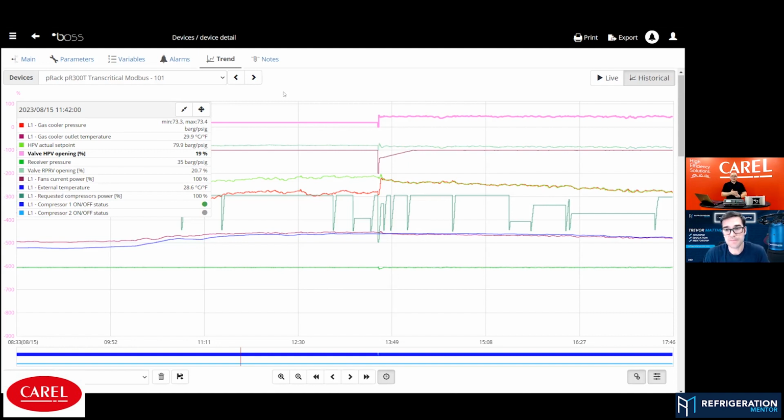Not really, not really. The problem was our friend in the service was a bit stressed and nervous. Yeah, and fair. He put up the motor of the valve while it was regulating. And he was not thinking about the controller has no idea where the valve is really working and opening. My controller was thinking, okay, everything is running. My valve is closing at the moment, and now it should be at 90%, and everything is fine. But in truth, the valve was in an opening percentage of roughly 30%. But the controller was thinking, I have reached my minimum allowed opening amount, and I'm not allowed to close it more. This was the problem.